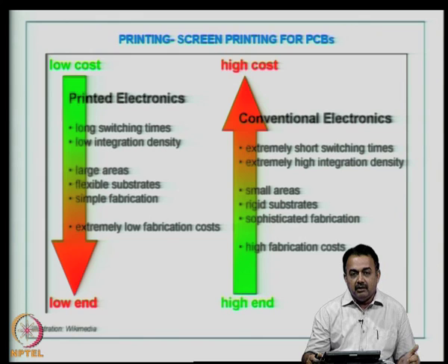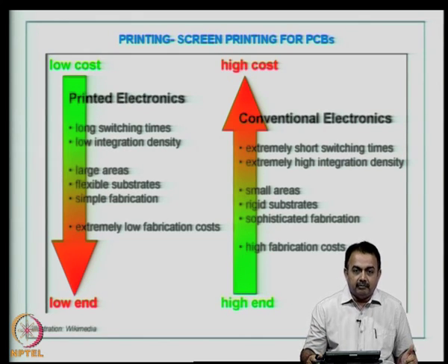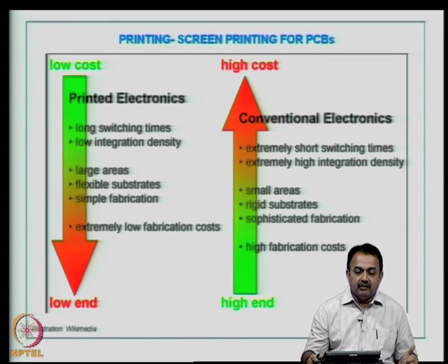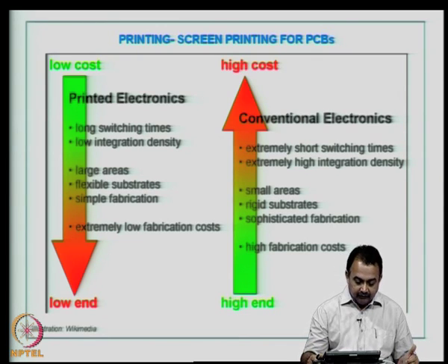This is normally used for commercial electronics applications, boards which have larger line widths and which obviously cannot be used for high density interconnects, although screen printing can be used for solder mask printing and legend printing as a finishing process in the high density interconnect or any kind of PCB structure, any system level printed wiring board.